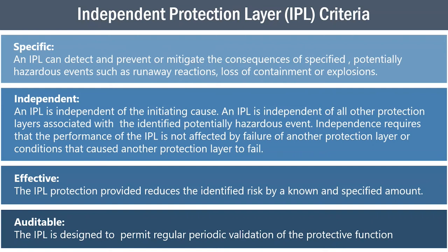Obviously, they're protection layers. One is based on an SOP and training, and the other is based on some sort of electronic readout of level. So those are independent. However, the actuating event of a person stopping the flow is still the same person having to hit that same button. So in an argument there, you would probably say that even though those two things are protection layers, they're not necessarily independent protection layers. And we'll talk more about this as we go on.